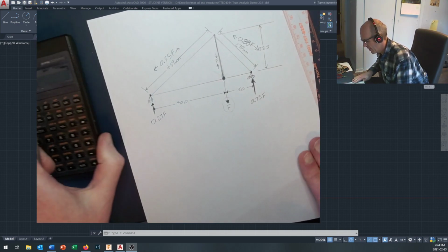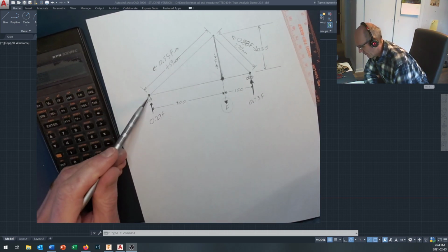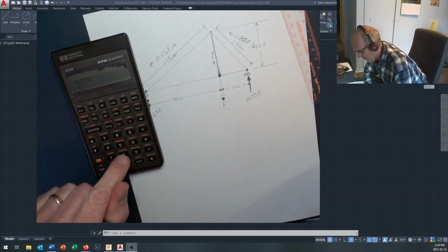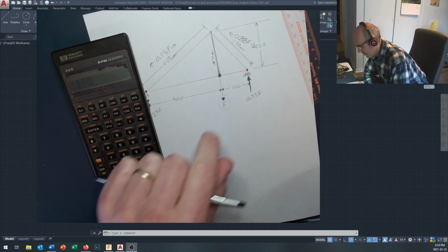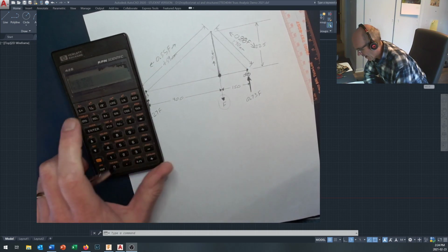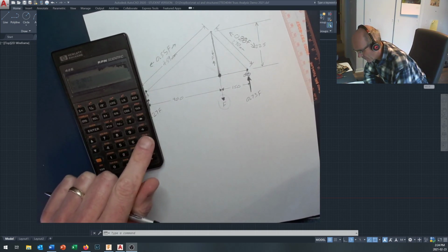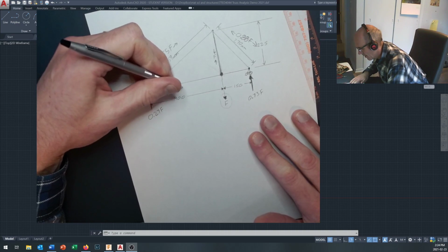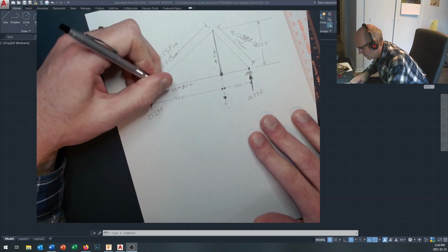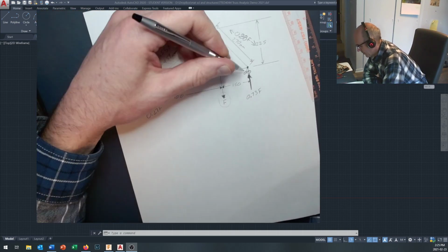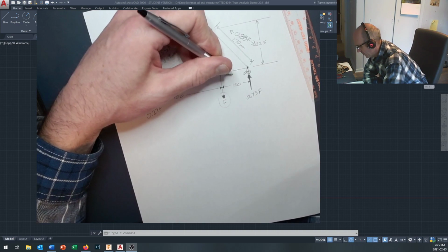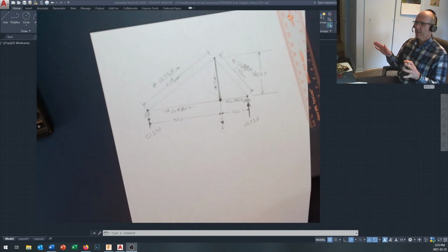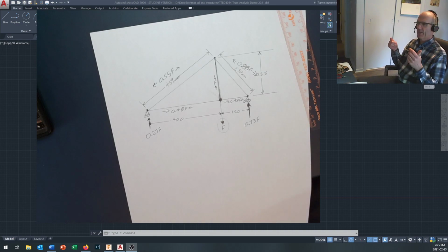And we can calculate the amount of tension force in the bottom right there by saying, well, over on this side, if I've got 0.27 F acting upwards right there, then 0.27, and that's acting in the 225 dimension, and then that's 400 long, and that gives me 0.48 of F in tension right this way. You can do the same calculation over here, and this one also better be 0.48 F.